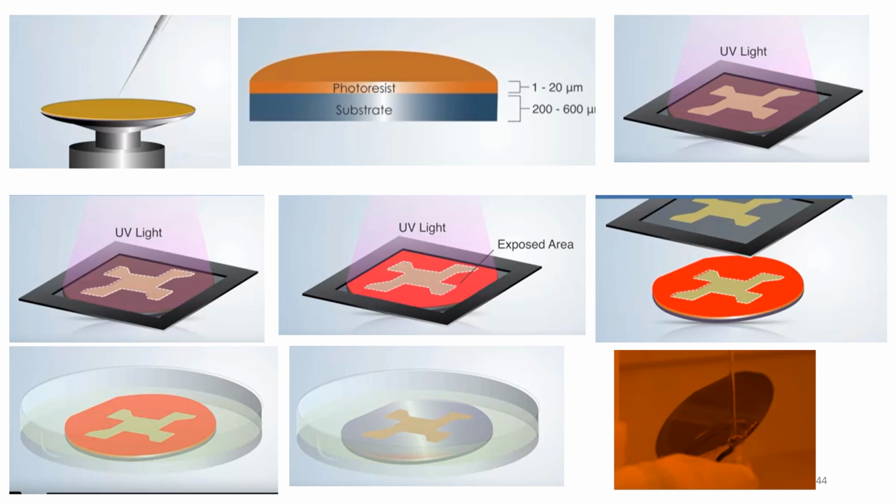And after this, if every region is clean, you only have the wafer, and on top of it the photoresist, and this has to be after etching. After, say, chemical wet etching, you only have the substrate and the gold on top of it, and this has to be cleaned, and nitrogen should be blown after this.